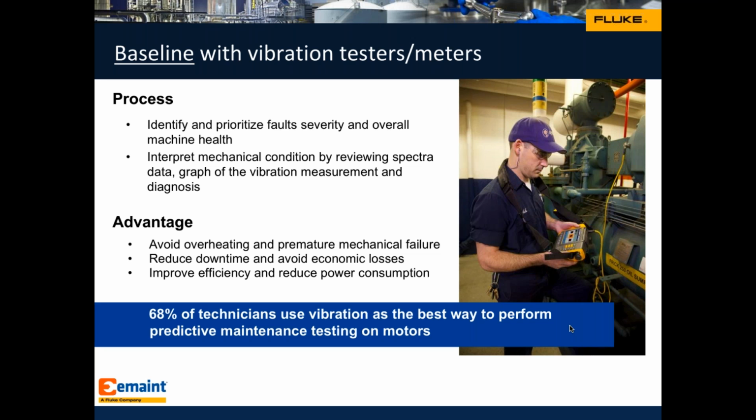And so I showed it to him, grabbed the data, uploaded the data to the cloud, and then we told him, you know what, we're not going to take the motor offline, but why don't we just add some grease right now and come back in 2 hours. And then we'll take the exact same data at the exact same spot, and we'll see if that makes any change. So we did this, and we were surprised to find out that just by adding a little bit of grease and doing a very quick screen check, we were able to find an issue, resolve that issue, and not have to take down the motors for repair, and potentially avoid a failure.